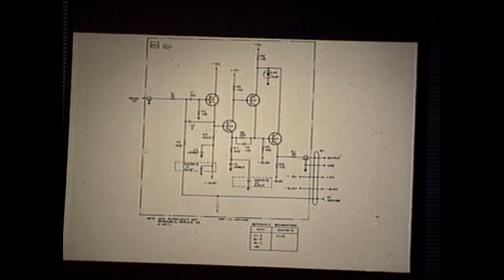Let's get a little more modern. This particular diagram has a special significance. Here's a FET. Here's a 2-transistor gain stage. Here's the feedback right here. This is a FET probe from Hewlett-Packard, about the 60s. Here's the collector, comes out right there. There's the feedback node. That resistor and that resistor set the gain of this stage. This is just a follower out to drive the cable up to the scope. That's feedback to a low impedance node. That's current mode feedback, circa 1965.